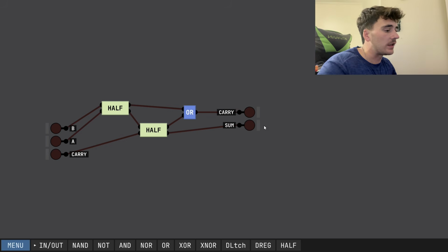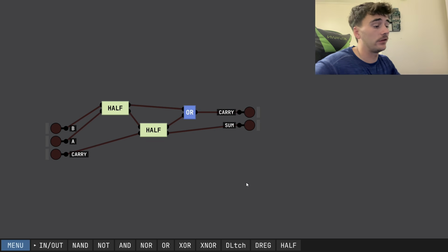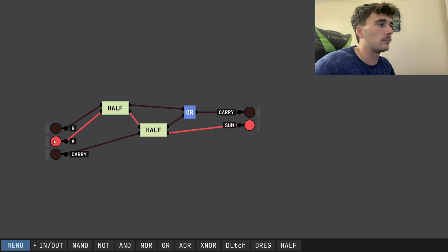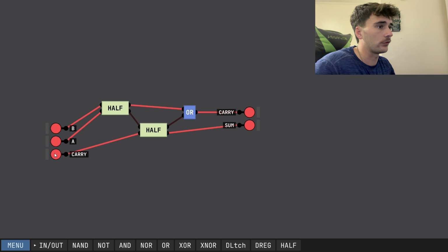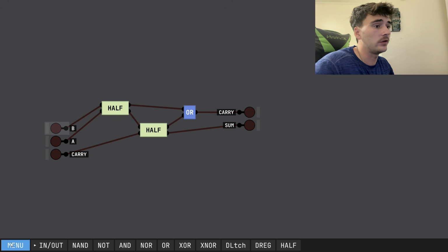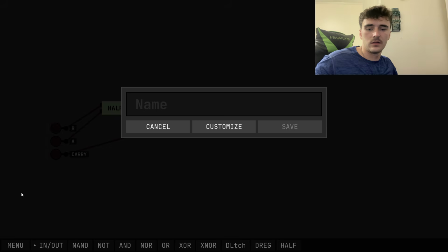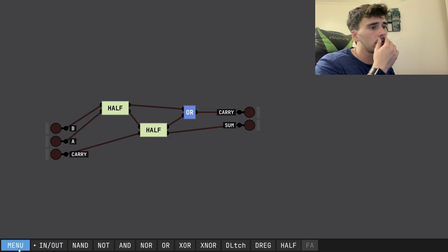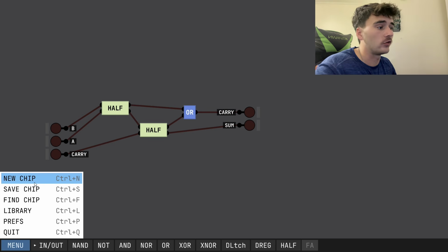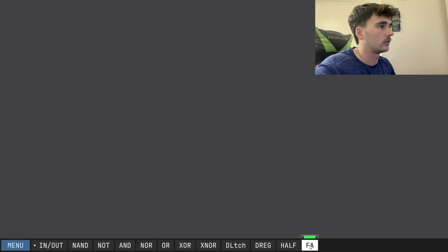So in case you think I did some little voodoo magic, it kind of is, not going to lie. But if this is all ones and then we count this as decimal and this is the ones place and this is the twos place, 1 plus 1 is 2, plus 1 is 3. This is 1 plus 1 is 2. And there we go. So we have a full adder. And then we can chain these up to make a 4-bit adder, which is exactly what we want.